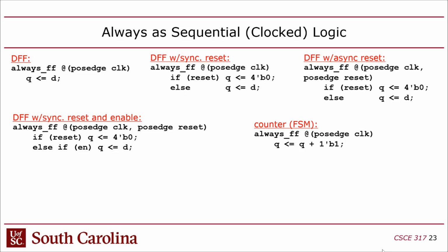Now the same thing happens, by the way, if you have an output in an always that you don't assign. So say you have an if statement that causes something not to be assigned. That also creates memory, although that's usually undesirable. If that happens, it's usually a bug. I don't think anyone ever intends and deliberately has that style of coding, right?